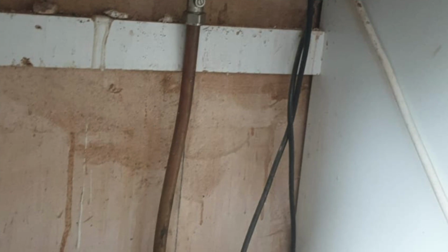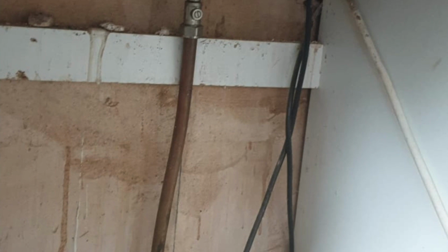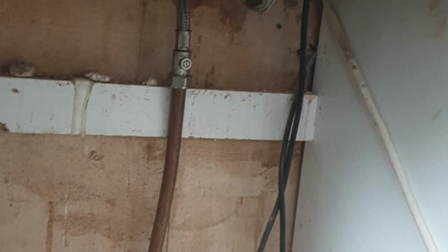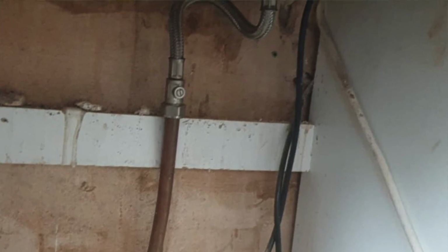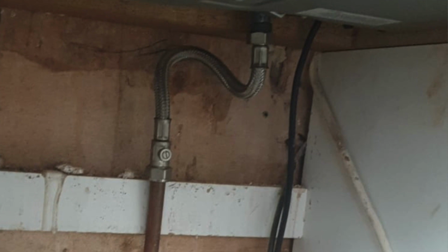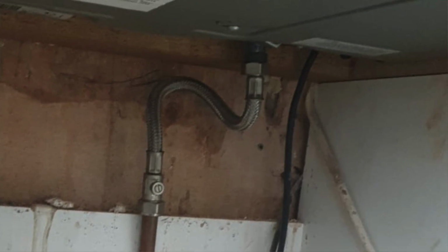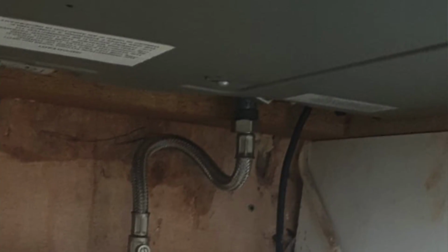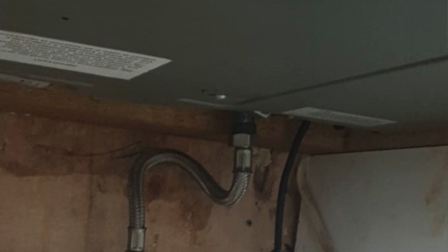Number one, ID and RIDOR for any plastic push fit fittings or hose pipes or any inappropriate fitting used on gas. Now in this scenario, you've gone to do a landlord's report, and you see there is a gas hob for an electric oven. So when you remove the electric oven, this is what you find. So this is how it is connected. On further investigation, you ask the tenant, when was this hob fitted? Because it looks brand new. And they said it was fitted by the landlord 2 weeks ago.